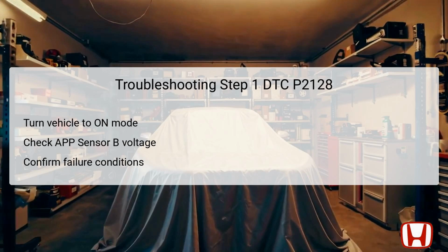However, if the conditions do not align with the expected values, it may suggest an intermittent failure, requiring the technician to inspect for poor connections or loose terminals at both the APP sensor and the PCM.